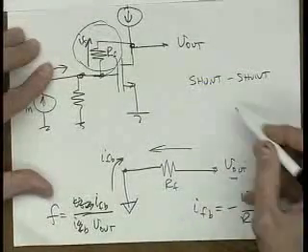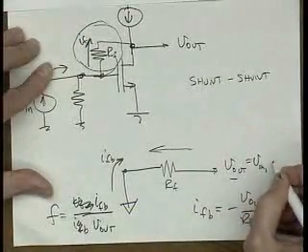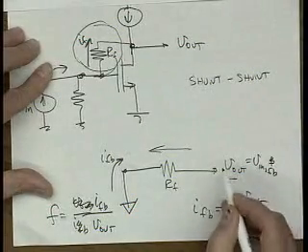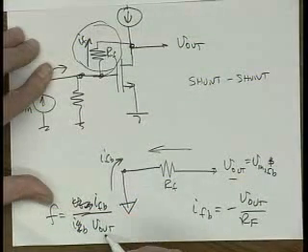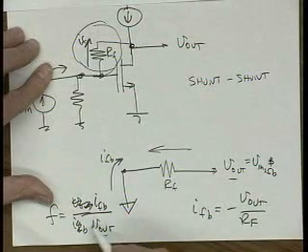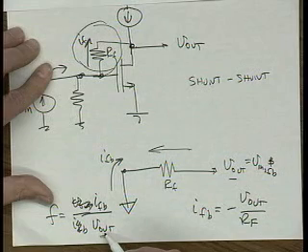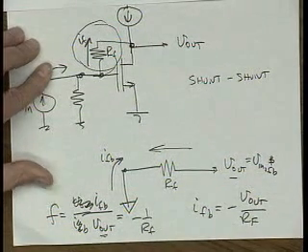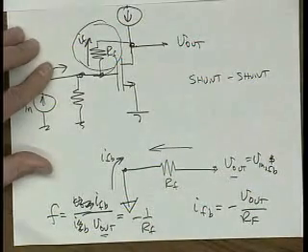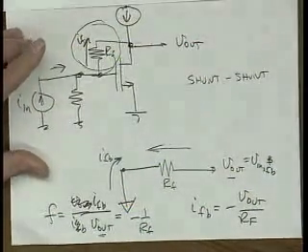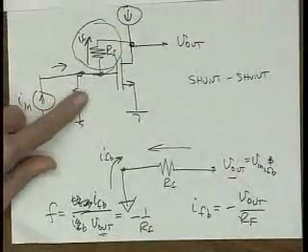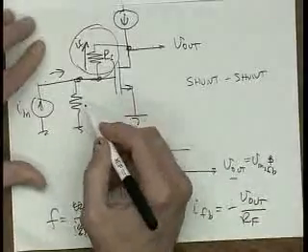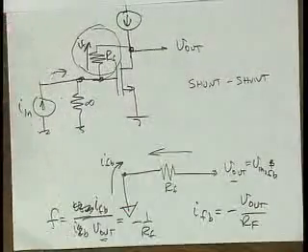Remember, this V out is equal to V in of the feedback network. Watch these V outs and so on. So I feedback over V out, which is V out of the closed loop circuit, which is the V in of the feedback network. This is equal to minus 1 over RF. I've left out this resistor right here for right now, and I'll care about this a little bit later. In fact, this could be infinity right now, so as far as we're concerned, don't worry about that one.